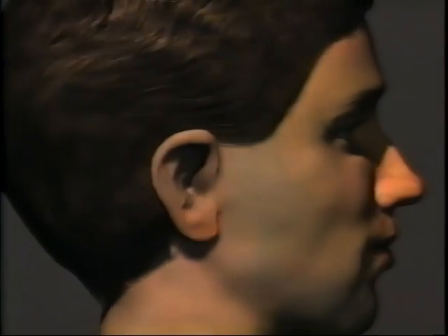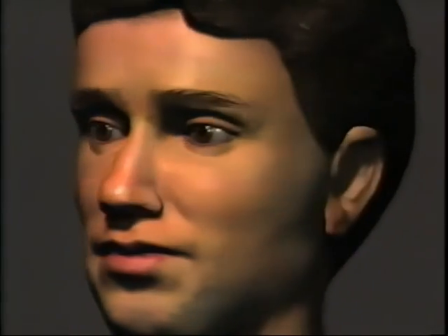If we preview him, we can see the highlights on his nose from the bright part of the specularity map, but not so much on his cheeks or chin. Specularity mapping works better than painting these highlights directly into the color map, because these highlights can travel across the face when the head is seen from different angles. We'll come back to this head in the last section to talk about how we animate it.